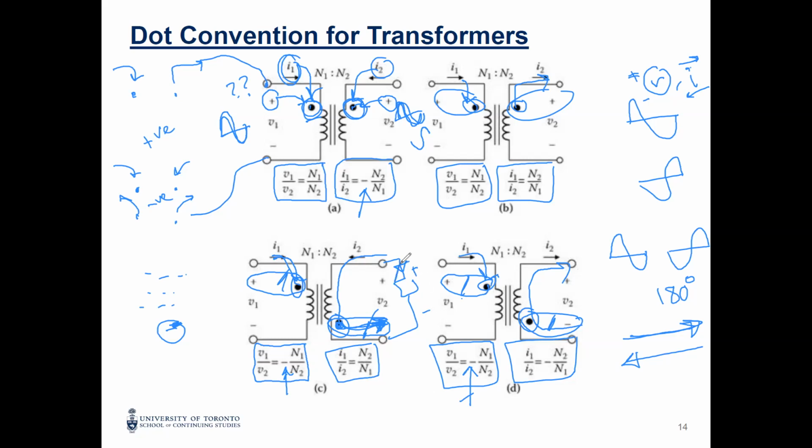However, if you assume that the current is going out from the load, you will find it will be the same current, but you will have a negative sign. It means it's a load, it's absorbing power, it's not generating. We call it generating power in negative, right? So it's absorbing, something like this. It's just the direction, the convention of the system that you are dealing with.